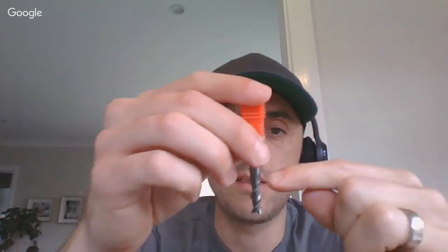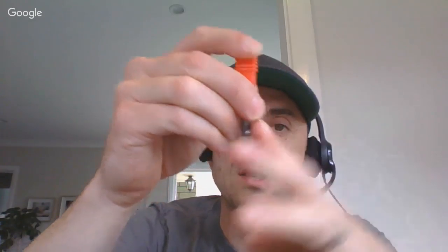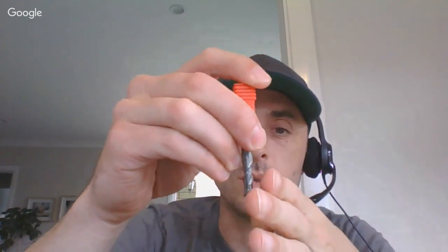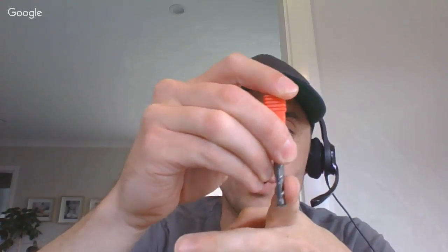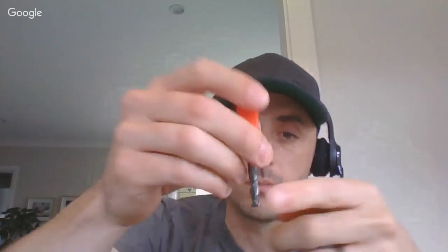Yes. Because of any loading or misalignment, there's a few things that go into it, but that deflection on the cutter is one thing I'm talking about. There's also deflection in the material. So when you take a heavy roughing cut and you push the material away to cut it, it does tend to spring back a little bit after the cutter moves past. So from a roughing cut, the amount of force or pressure you've exerted on that surface means that you're not going to end up with a very accurate position of that wall once the cutter moves past.